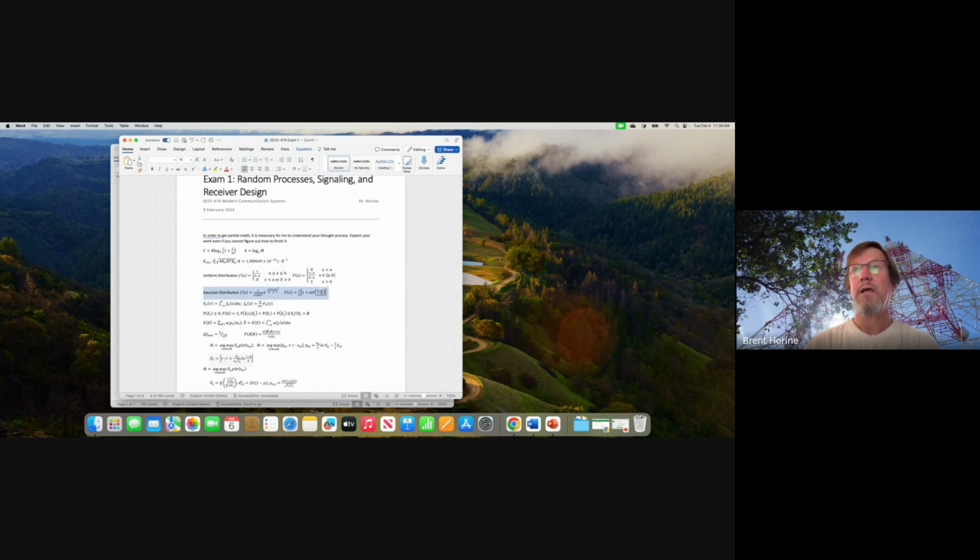So you might be given an equation like this, and you need to recognize that this is Shannon's capacity theorem, and that the capacity gives you results in bits per second, that this is the bandwidth, and this is the signal power and the noise power, right? And to be able to recognize that if you want to increase the bandwidth, the capacity increases overall. That's kind of our job as communication engineers.